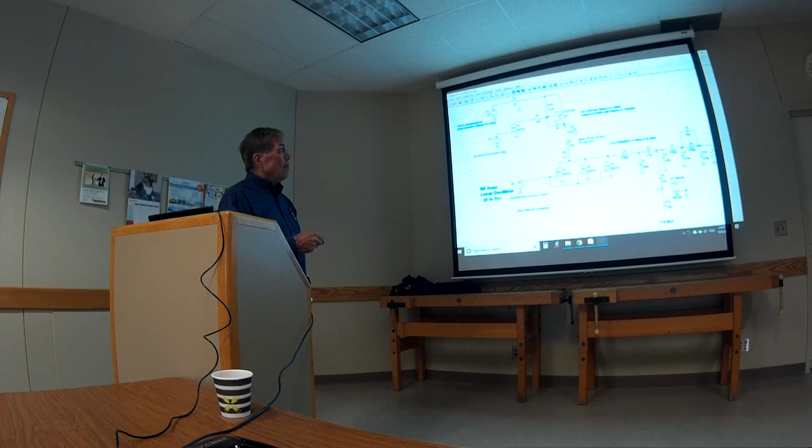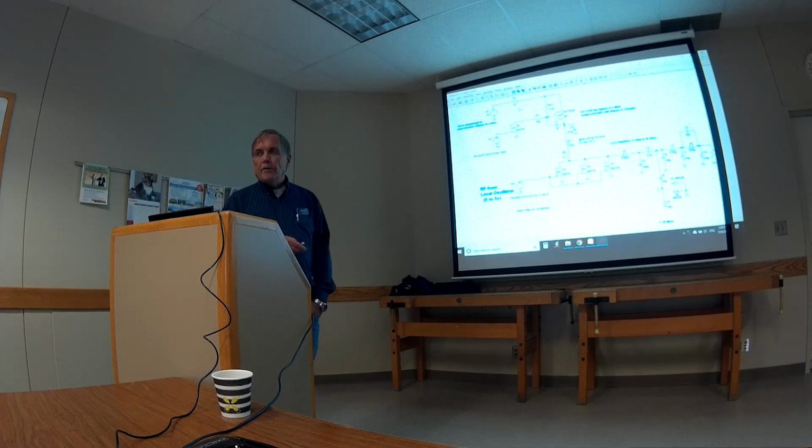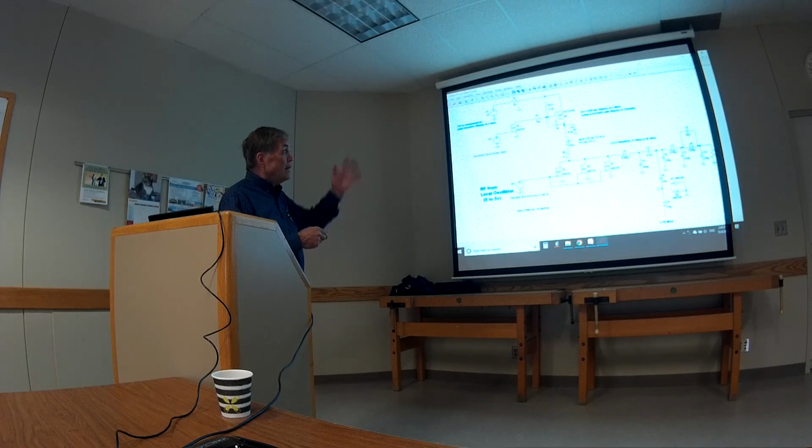The one I'm actually looking at is an NTD2955, and it's only 155 milliohms across it. So it's a really nice part for not too much power, and I can hook that in instead and run this. I upped this voltage a little bit here because of this resistance, just to see that the output is about comparable.